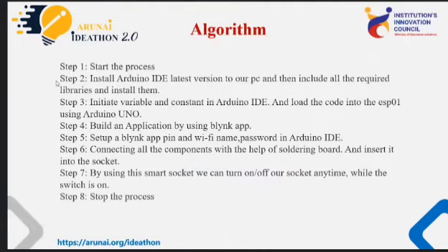Now I'm going to explain the algorithm. First, we will start the process. Secondly, install the latest version of Arduino IDE on our PC, which includes all the required libraries. Next step is to initialize variables and constants in Arduino IDE. After initializing this, load the program to the ESP01 using Arduino UNO.